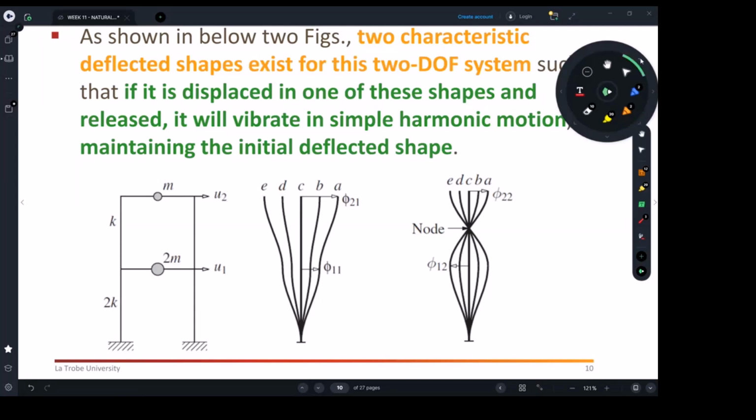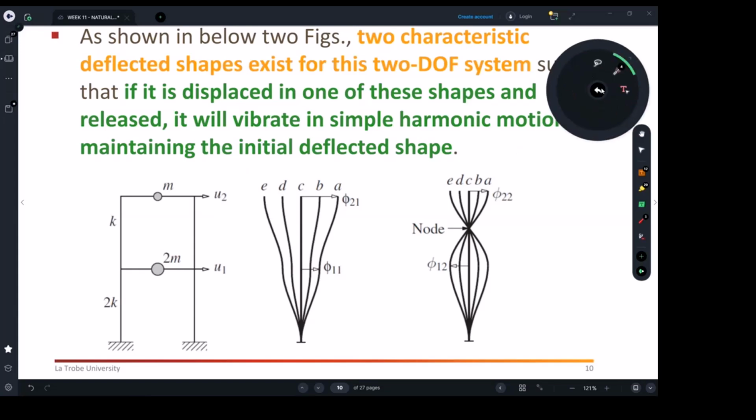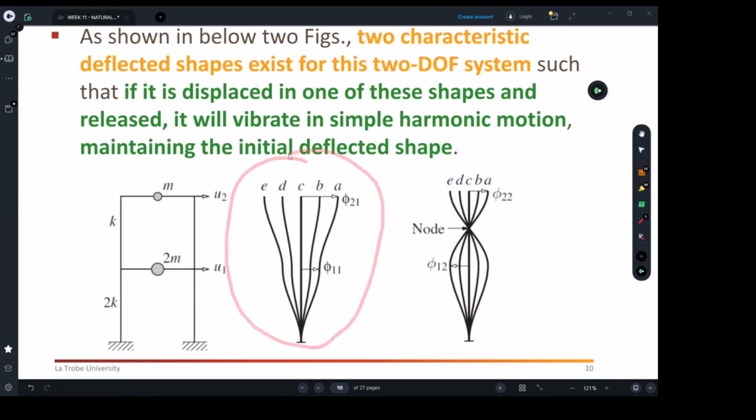So the most severe mode shape is actually the easiest shape to be profiled, and it has the highest time period and the smallest frequency, because it's the gentlest vibration. It's really the most severe one to worry about as a designer.